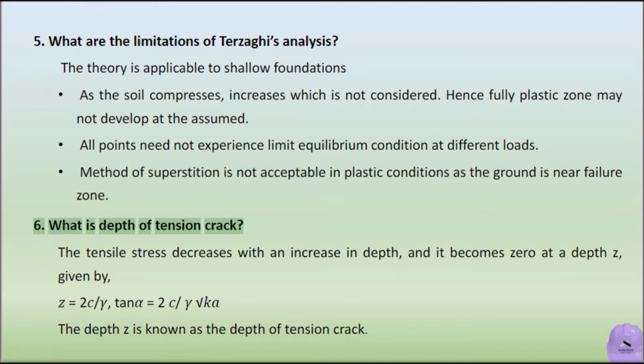6. What is depth of tension crack? The tensile stress decreases with an increase in depth, and it becomes zero at a depth z0, given by z0 equals 2c over γ times the square root of Ka. The depth is known as the depth of tension crack.